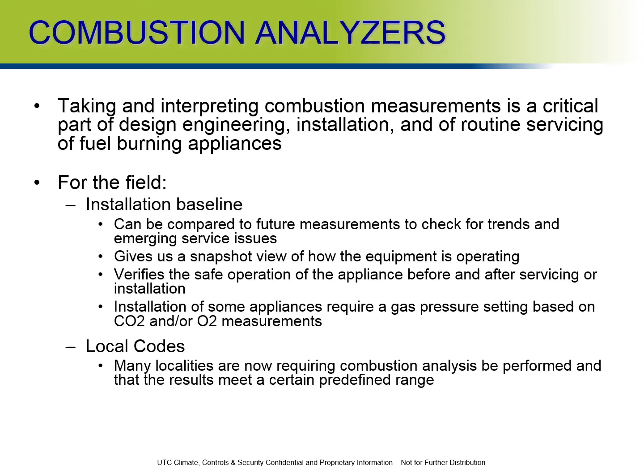And you may also have to make some gas pressure adjustments, based on the CO2, carbon dioxide, or oxygen measurements, because not all gas from the gas supplier is the same. Some BTU contents are more than others, so that could come into play when taking your measurements. And on top of that, a lot of localities are now requiring combustion analysis to meet certain criteria to be good to go.